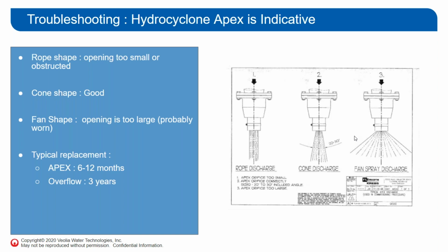Charging up and up and up and cycling up, and you'll eventually have a perfect process, but keep building up your sludge blanket in your settling tank despite all your perfect efforts. And yeah, it's because your sludge isn't being evacuated out through the top of the vortex finder, and it's coming down through your worn apex tip.